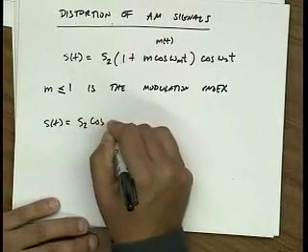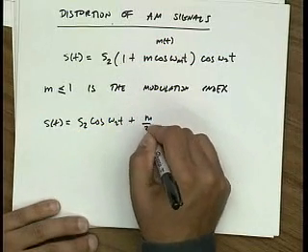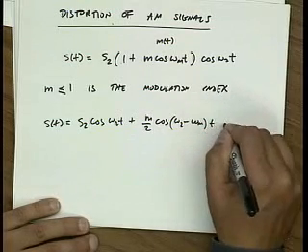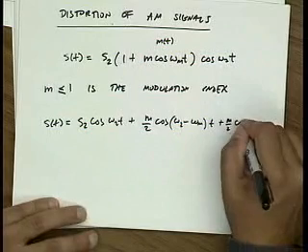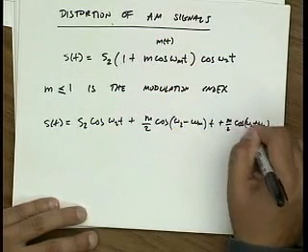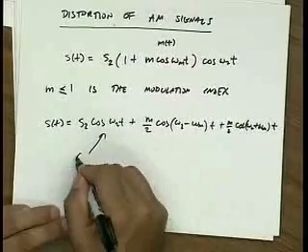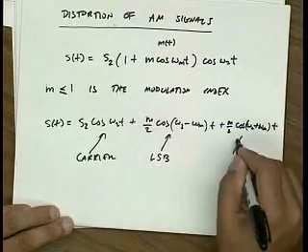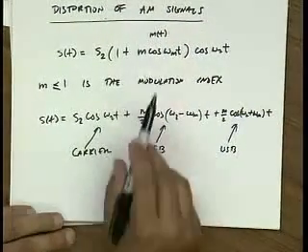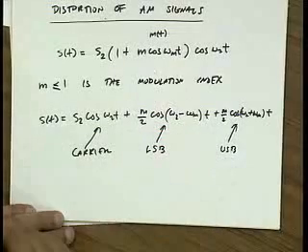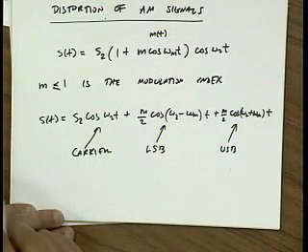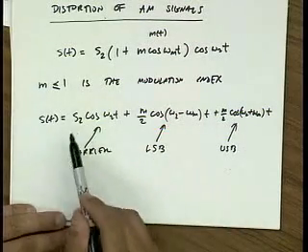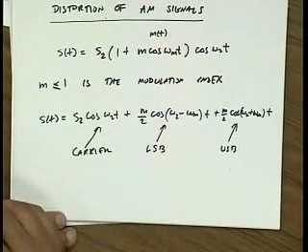And so I can expand this product out using cosine 1 times cosine 2, which is sum and difference cosines, and I get basically three terms: m over 2 cosine omega 2 minus omega m t plus m over 2 cosine omega 2 plus omega m t. So this is the carrier. This is the lower sideband, and this is the upper sideband. So we see that this modulation waveform produces two sidebands around the carrier, and there are lots of variations on how the signal is sent. Sometimes the carrier is suppressed. That's called carrier suppressed amplitude modulation.